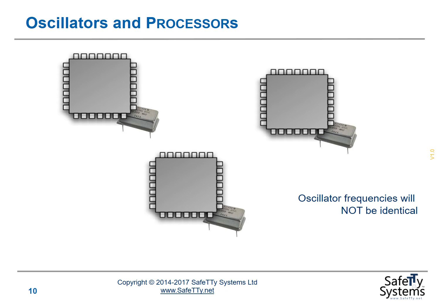There's no links between the microcontrollers. Let's say I connect a heartbeat LED to each microcontroller, run identical code in each microcontroller, go off, have lunch, come back. The heartbeat LEDs will not be flashing at exactly the same time. There'll be some differences in the oscillator frequencies, and my various processors will not be synchronized.